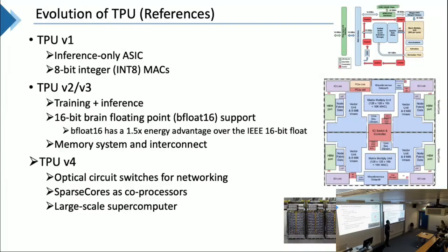And once you have this sparse matrix, you want to skip the computation of zero elements because they are wasting your clock cycles. So that is another feature called the sparse tensor core. They introduce this sparse tensor core as a core processor to accelerate sparse matrix multiplication.